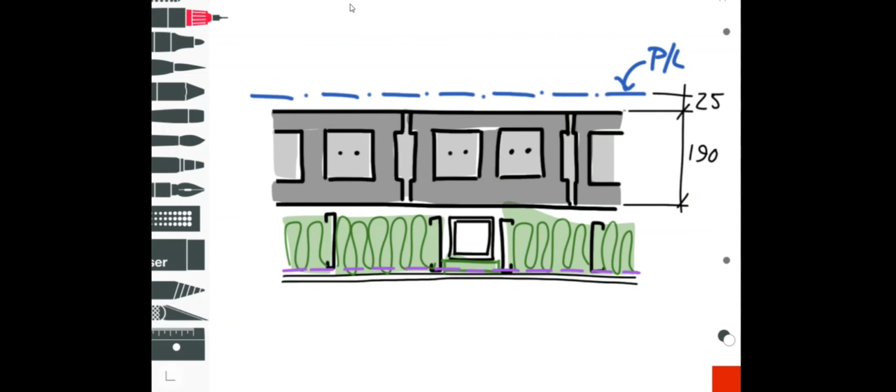Okay, so how is this insulated? What I've drawn here is generally how it might be done in a normal instance. It's not good, so we will improve this for sure, but this would be the cheap and nasty, I suppose. Again, this is assuming you don't have access to the other side of the wall and you can't insulate on the outside. So I've just left an airspace here, 25 mil or so, and then a steel stud wall is built around the steel column, which is right there. And of course, there'd be beams above that the studs would go to the underside of.